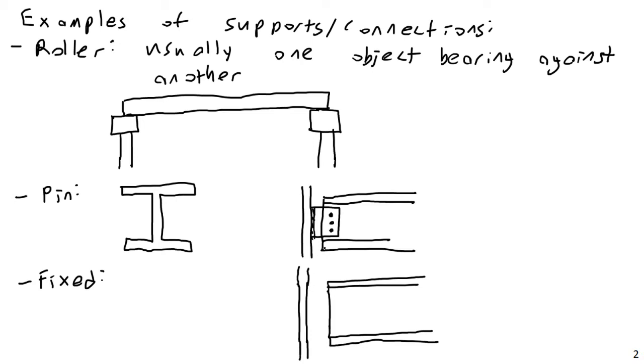Although the one case you have to be careful with, probably the major case, is where you have a continuous beam. If you had a continuous beam going across multiple spans and you assumed those were simply supported, just pin, pin, pin to be lazy and make analysis easy, that could potentially cause a large problem, because with continuous spans, as we'll see later in the semester, you can very easily get negative bending moment. If your beam does not have identical positive and negative bending moment capacity, especially concrete beams, that can cause a big issue. Assuming pin support, pin support, pin support is actually not a conservative assumption for the case of negative bending moment. Maybe that doesn't make a lot of sense right now, but we'll get to that in a bit.